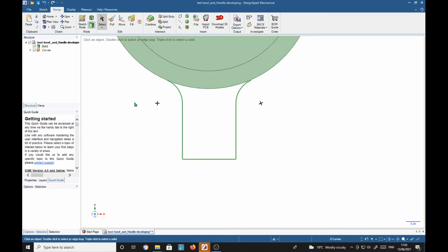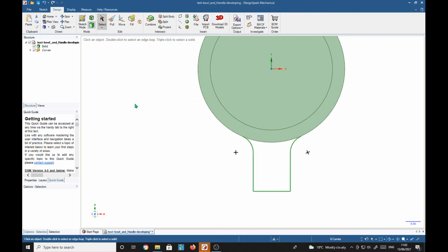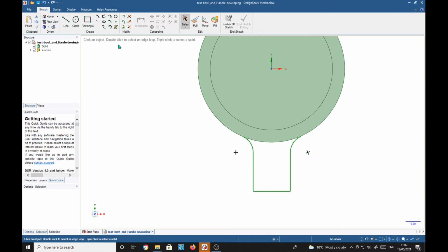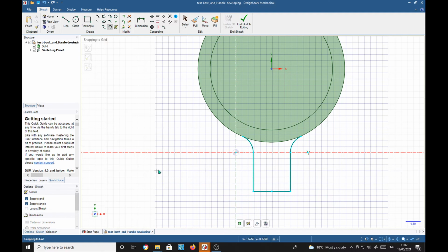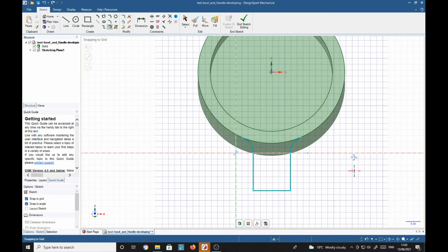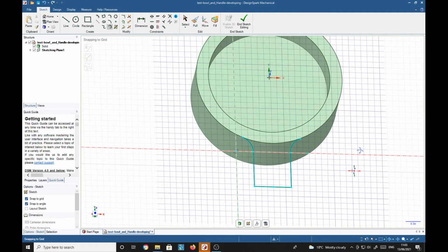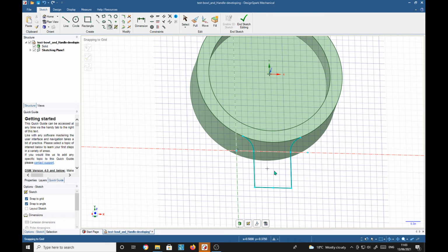Okay, so what I did was to use the sweep arc and wait a moment. It's put the surface where we wanted it, which is at the same level as the handle, because it was already selected, so we're good to go. So the sweep arc is selected.